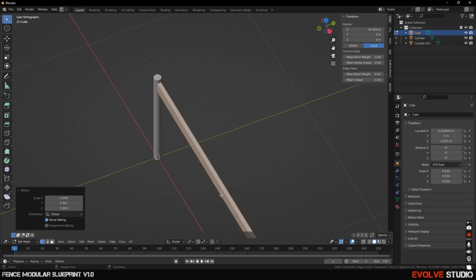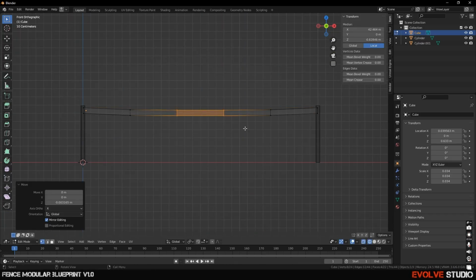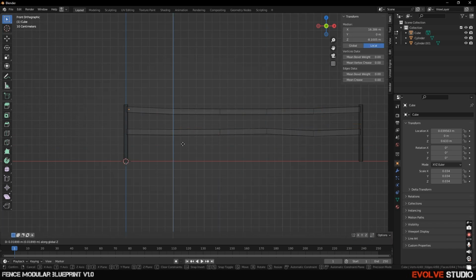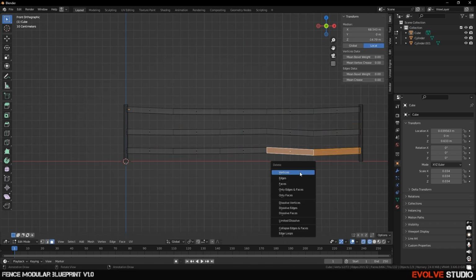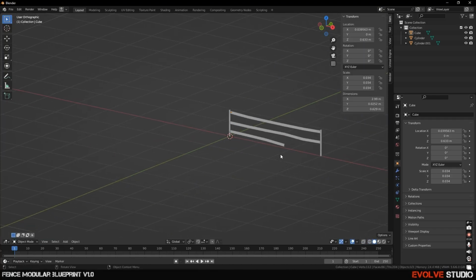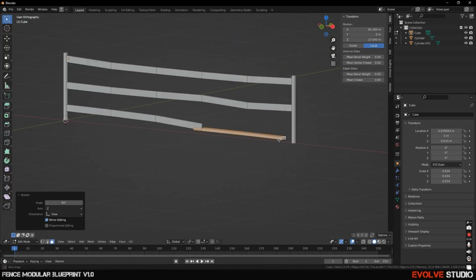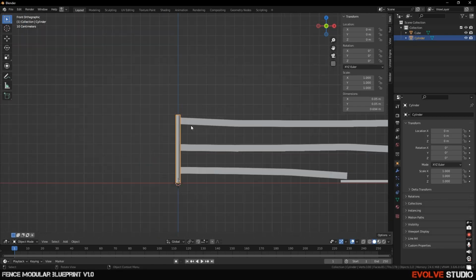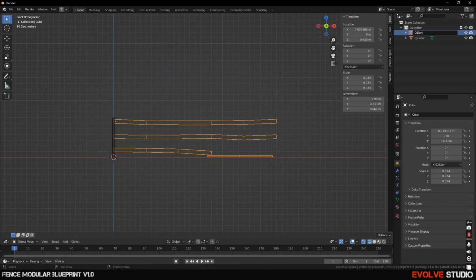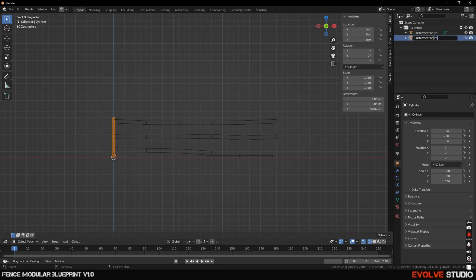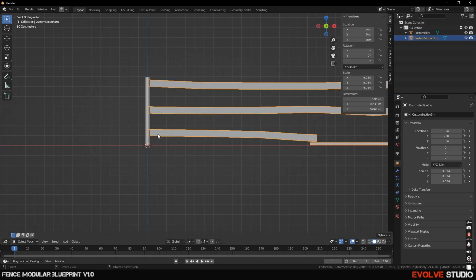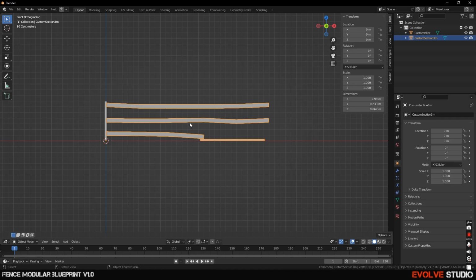By default, you would want to make 3 section lengths: 3, 2, and 1 meter, and also a pillar model. I recommend building a rounded pillar, as it will allow you to make any angle of the fence. The pivots for all the assets should be placed at 0.0.0 world coordinate. To be sure you are calculating the section's length right, just duplicate your pillar and drag to 1, 2, 3 meters to the right. This will give you a good understanding on connecting the fence to the pillars. Make sure you reset the scale and rotation to default.